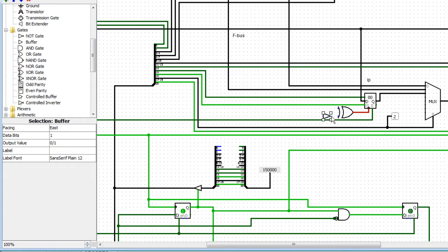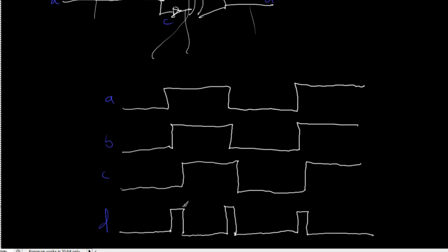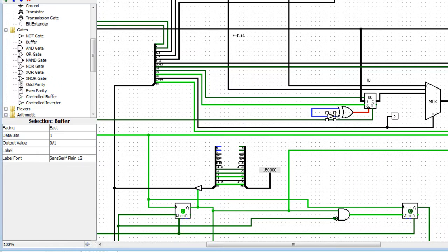Generally, you'd probably want to add a few buffers. Alright, Papa's not here. But anyways, normally you'd want to add a few buffers here because you might want your pulse to be a little bit longer. Because circuits might need some time to respond to the clock. There might be a hold time requirement for the circuit. But in this simulation, we don't have those requirements, so I'm just going to put in one. Because the less gates we have in our circuit, the easier it is for my computer to simulate this and the faster it'll run.